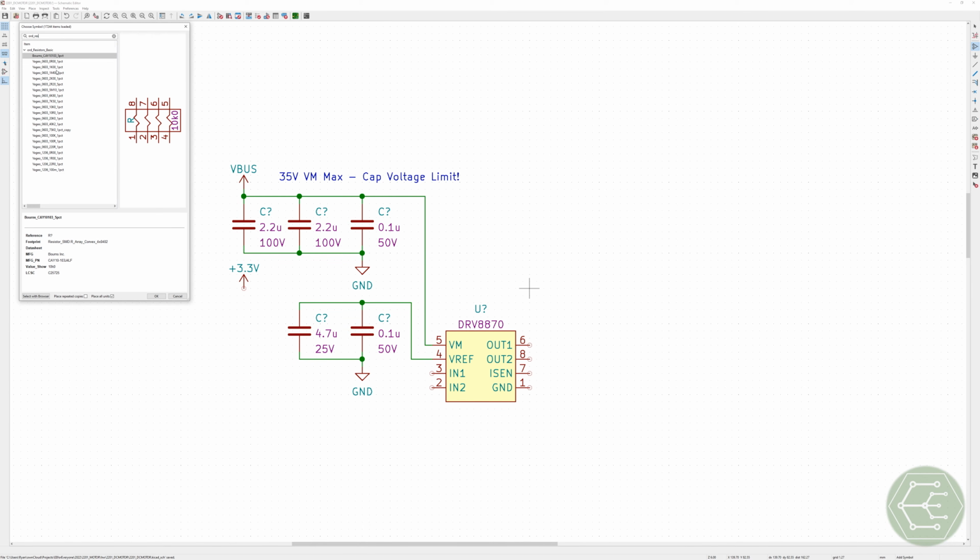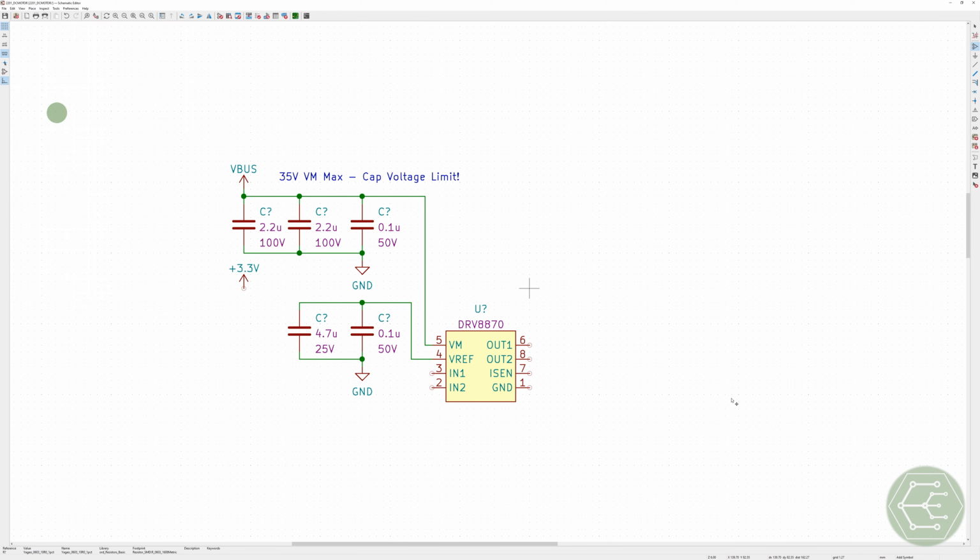so let's grab some small value, something not too crazy. Let's go for a 10 ohm. I still want it to be the right voltage. I just don't want ripple to get through. So you put a bunch of capacitance close to the IC, you add a series impedance, and that does you all right. Could be a ferrite bead, that might work better, but since I know the load, right, this load is a microamp or two, according to the datasheet, I'm not too worried about that.